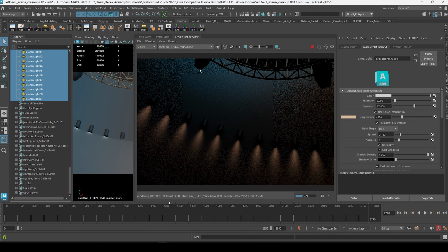And hit F8 to go into component mode. And select all the components. Then my W key, make sure I go to object mode, and I'm going to move all of them back so that they're inside the wall a lot more. I'm going to turn on the environment to see, okay, that's too far, so I'm going to move it like that. It doesn't matter that I leave the light behind, so like that. Okay, so that looks like the type of fixture that's just a half circle. It just makes it integrate into the background better.